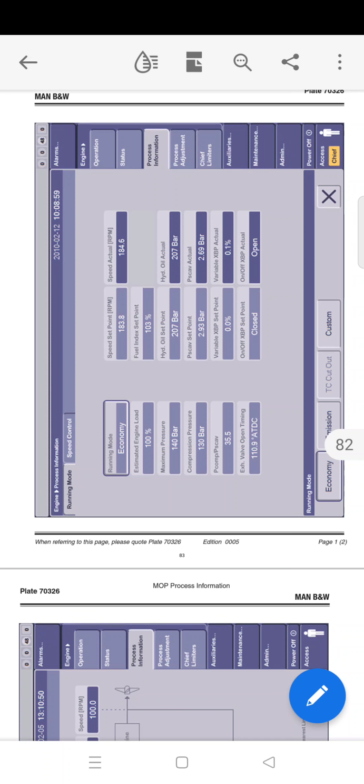And the engine running mode is based on an algorithm which continuously determines the fuel injection and the exhaust parameter that influences the cylinder process. By controlling the cylinder process, maximum cylinder pressure, compression ratio, and blowback, fuel efficiency and emissions can be controlled to a certain extent. For the ME engines, several running modes may exist. These contain different algorithms and provide various fuel efficiency and emission characteristics. The running modes are configured for each engine type by MAN B&W.